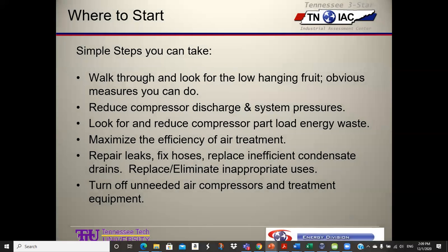Reduce compressor discharge system pressures. Look for and reduce compressor part load energy waste. Maximize the efficiency of air treatment, your dryers and your filters. Repair leaks, fix hoses, replace inefficient condensate drains, replace and eliminate inappropriate uses, turn off unneeded air compressors and treatment equipment.